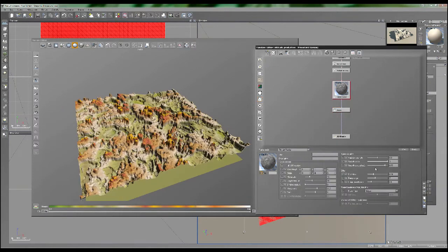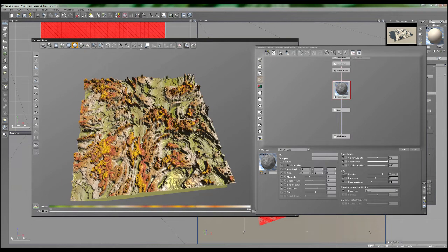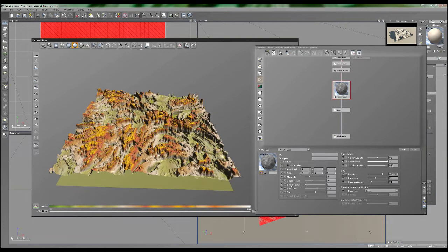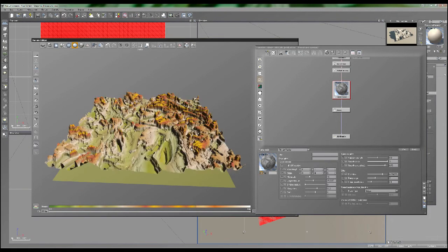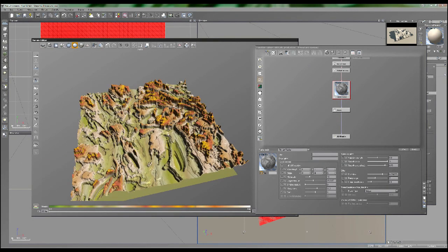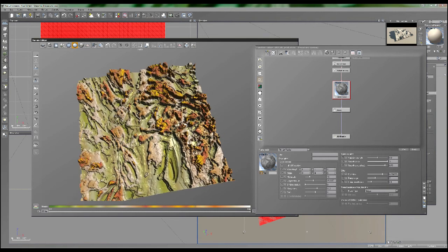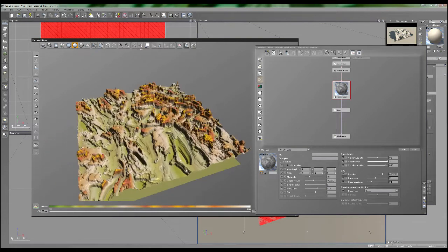So, I'll probably have to change around some of the details of the main fractal. I've turned up the distortion, which gives us these nice waves. Let's turn up the largest feature as well. There we go. I had too many small features. I want to get some global striations here and see these sweeping lines coming through our terrain. So I'm pretty happy with that.